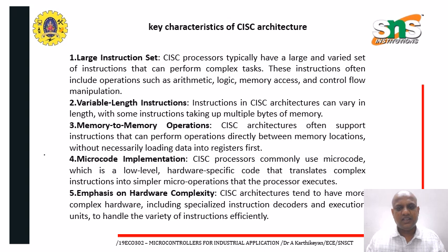The key characteristics of the CISC architecture are mainly a large instruction set, variable-length instructions, memory operations, microcode implementation, and an emphasis on hardware complexity. Compared with the RISC, the CISC has a somewhat larger instruction set, and it performs complex tasks. Basically, the RISC has a reduced instruction set, but the CISC has a complex set and can do multiple complex operations.